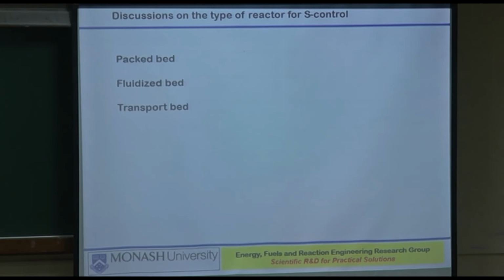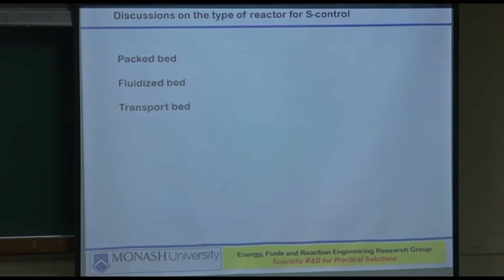At the start of the operation and for certain periods, when everything is fine, it will all be giving you a consistent set of pressure drops. But over a period of time, the pressure drops will start changing. You cannot expect that the flow in here and the flow in there will be exactly the same, because your catalyst particles are also undergoing attrition over a period of time.